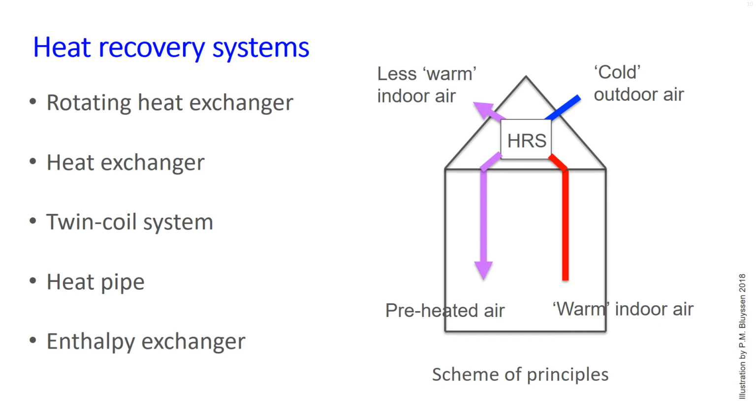Heat recovery can be an efficient way to save energy while maintaining a good quality of the indoor environment. The aim of heat recovery is the recovery of heat from return air by the supplied air. A number of appliances are available to recover heat from air used from ventilation. With the exception of rotating heat exchangers, those heat recovery appliances are no source of pollution because of their closed nature.